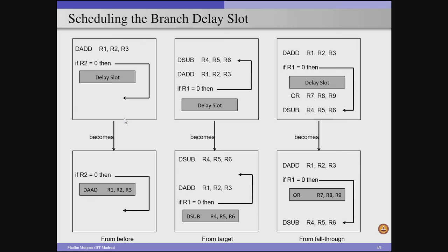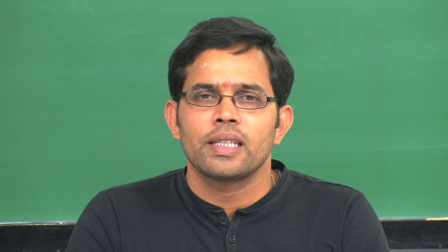program. So effectively, with the help of the underlying implementation for handling the branches, the software or the compiler can rearrange the program code in such a way that it can fill the delay slots with useful instructions and then minimize the penalty associated with the branches. And as I mentioned earlier, because the branch penalty is significant and it is critical for improving the overall performance, we have to minimize the branch penalties. And once we do that, then we can get a significant performance improvement.